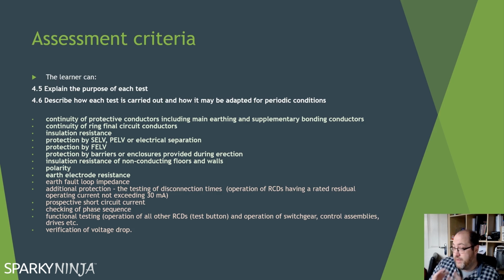And if you think of the regulations, do remember those 3 things that you must verify with polarity. The wiring regulations will tell us that the center contact of the ES lamp holder must be line, the outer thread must be neutral. We must make sure that single pole switches are switching in the line conductor only, and correct connection of accessories and so on. And I'm going to do another video sooner or later, but there is a big problem with the R2 adapters creating a bit of a polarity problem when testing, which I'm going to cover in another video at a later date.